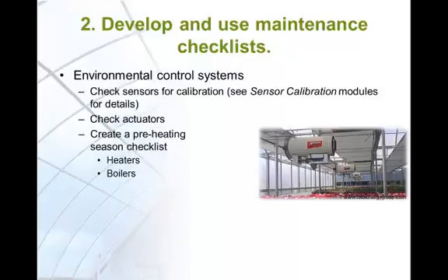For oil burners, flame monitoring devices need to be cleaned of soot. Spark should be checked for strong operation. Safety devices should be checked with a test light or multimeter. Horizontal airflow, or HAF, fans should be checked.